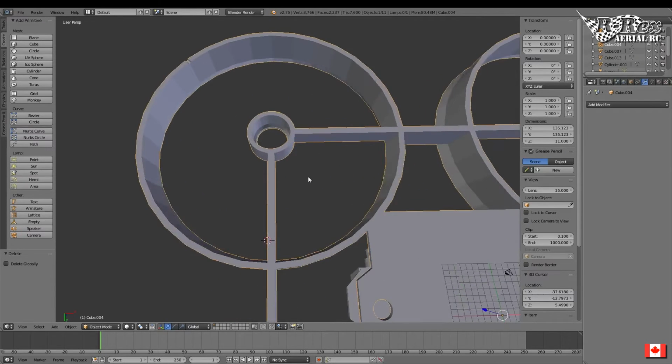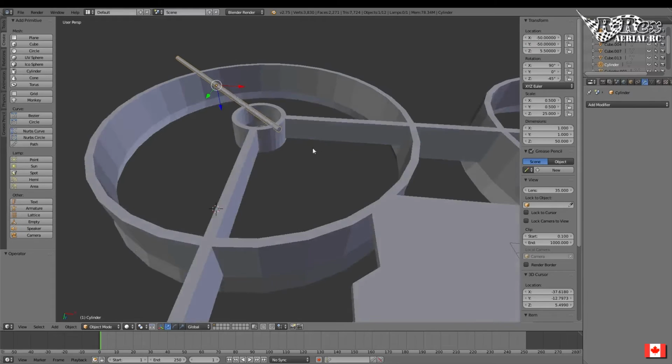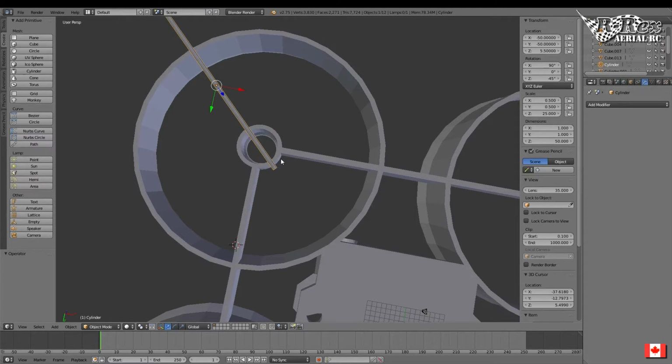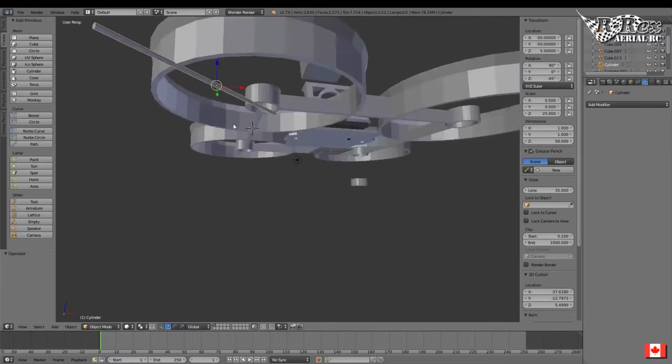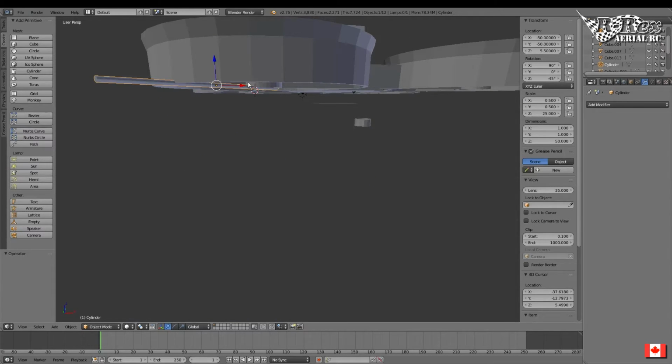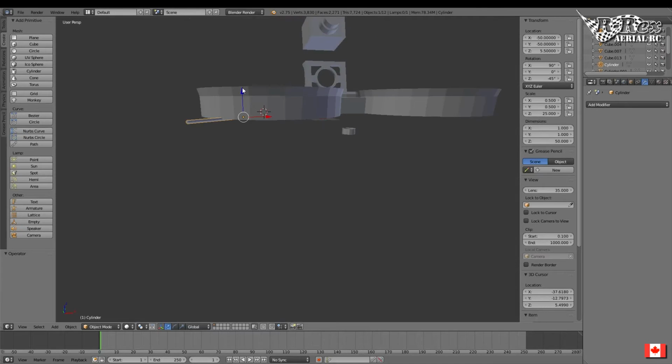If you were concerned that there might be an issue here, what you could have done is made this cutter, let's say, 50 long and negative 50 by negative 50. And what that would do is a brim on the inside, a brim on the inside, and brim all around, right? You don't really lose much. You basically lose that first layer. By the time it adds the material in for the brim, it's going to fill up that space anyway. So this is just for basically forcing the printer, or telling the slicer, to add brim on the insides of the objects.